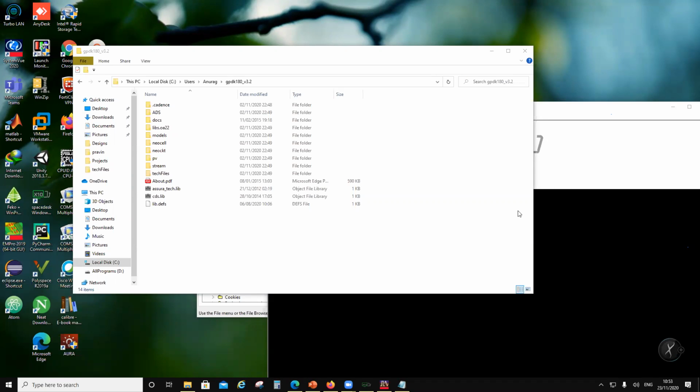So you do not have to model the passives. You can run an EM simulation on them and bring the data set file into circuit simulation, and do a co-simulation of circuits along with the passives.